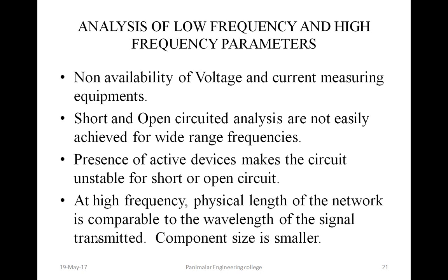frequency parameter analysis. So in order to do the high frequency parameter analysis, we need to necessarily introduce a new concept called scattering or S parameters. This can be understood like this. These scattering or S parameters are linearly related to the amplitudes of scattered energy, which is nothing but the reflected or transmitted waves of those incident waves.